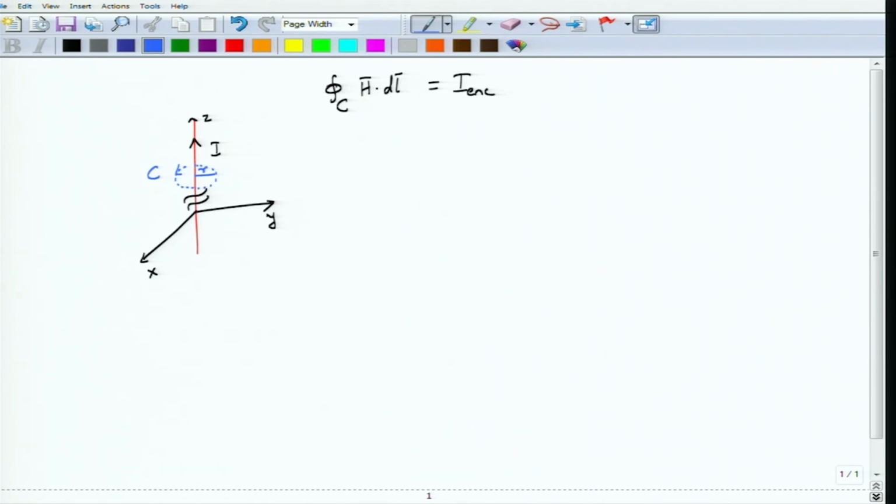Okay, so if you cut this z plane and look at the top view, this is what you would find. The top view would show you the contour, and then there is a central piece of conductor, or the wire, which is carrying a uniform current of I. Now for this contour, we know that in the cylindrical coordinate system, for constant z and constant r, the line element dl will be equal to r d phi phi hat. Of course, it is the angle phi which is changing, and your dl line segment will be directed along phi hat.